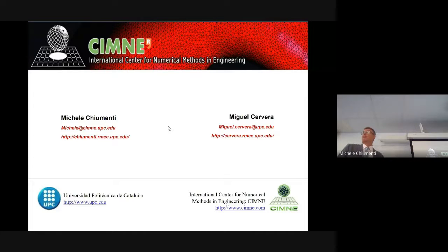Okay. I have one question. I'm just curious, would it be straightforward to implement these techniques in the particle finite element method to obtain mesh-independent results? In the particle method, it is not straightforward, and I don't know why you would want to do that, because particle methods use a completely different kind of balance equation and constitutive equation. In fact, you are using rigid movement of the particles, and then the constitutive equation is through springs or whatever between the particles. Right.